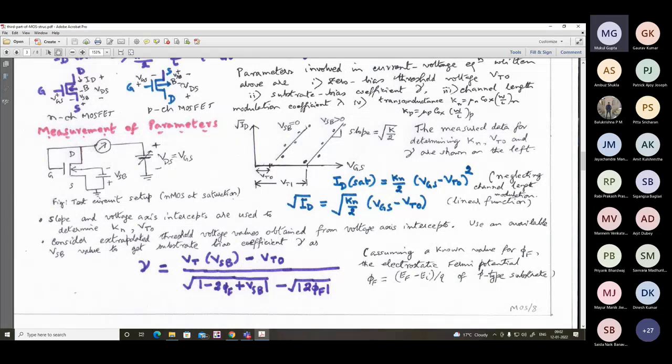Then for the bottommost transistor, the source is connected to body. But as you go higher up, the second transistor, third transistor, the difference of source and body potential will rise. So by mistake, this ground should be on the body side, not on the source side.